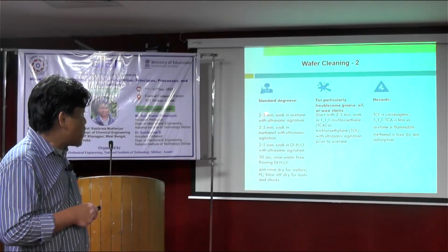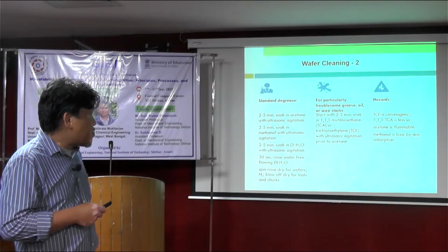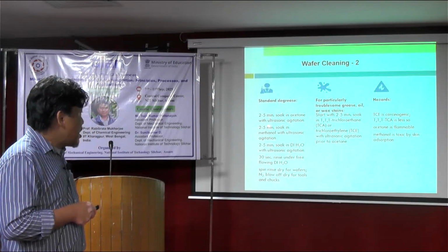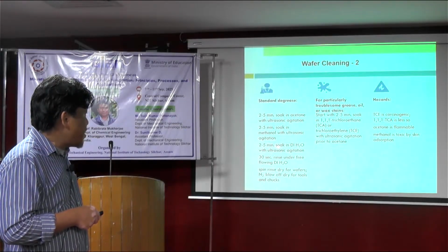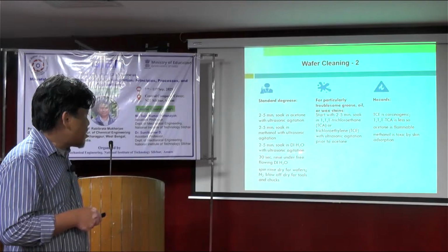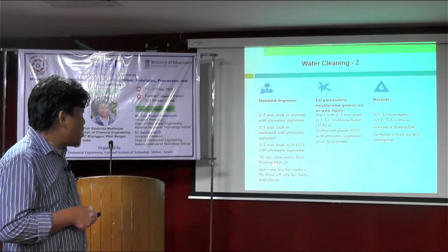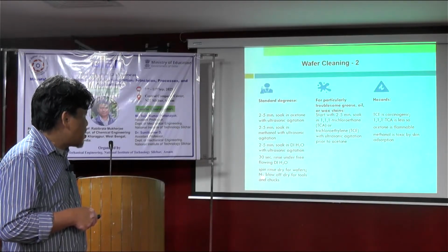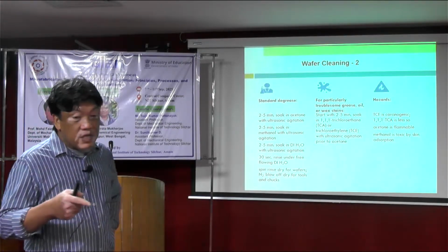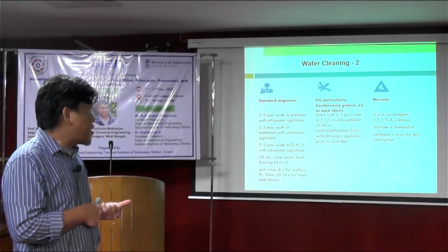The process is 2 to 5 minutes soaked in acetone with ultrasonic agitation, so an ultrasonic cleaning process, then 2 to 5 minutes soaked in methanol with ultrasonic agitation, and 2 to 5 minutes soaked in DI water with ultrasonic as well, then a 30-second rinse under free flowing DI water, and a spin rinse dry for wafers, with a nitrogen blow off for tools and chucks. We normally use nitrogen in the clean room to blow the air or to clean the surface.